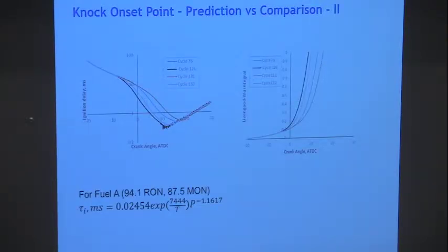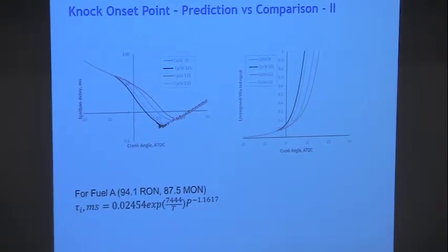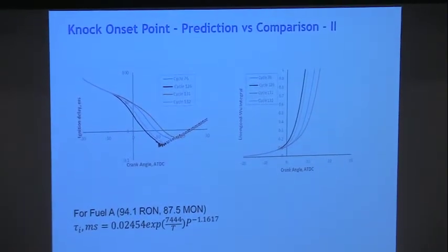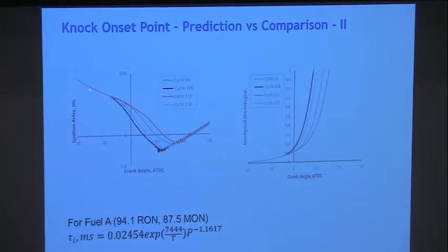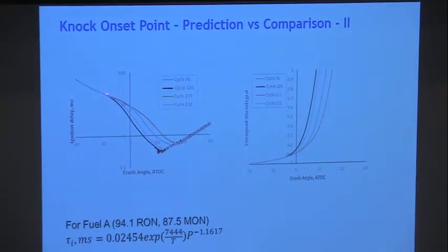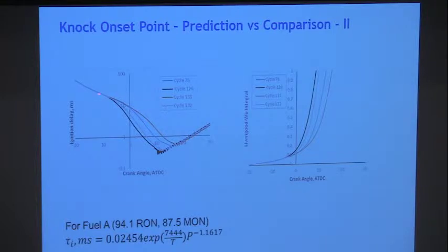and so we can calculate the ignition delay now. How the ignition delay is changing with crank angle. This is how it's changing. As the pressure and temperature increase, the ignition delay decreases because it becomes more reactive. And you can see here, this is the compression stroke before the, and you can see that beyond this point, our model really is from like 15 milliseconds down. Really, we've ignored everything.